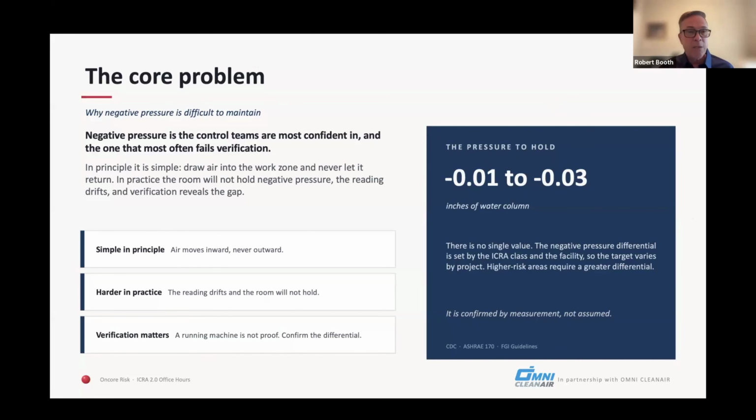Now, I survey a lot of hospitals and work with a lot. I see everything from 0.01 negative pressure, that's inches of water, to 0.05. 0.03 is the Canadian standard that we reference when we talk about this in the class. 0.01 is the negative air requirement from the CDC for TB isolation rooms or special respiratory isolation. Personally, I don't think that's appropriate. However, I do see that from time to time. The literature shows that 0.03 to 0.05 is protective, but it's really up to the hospital.